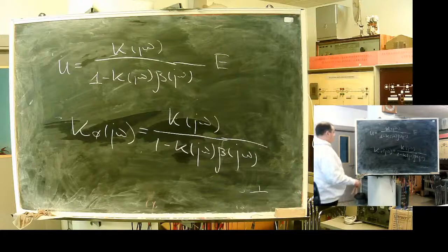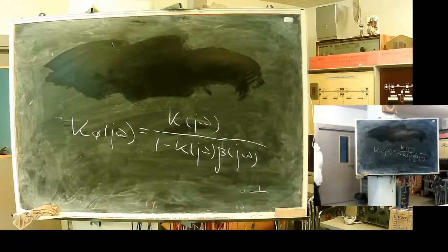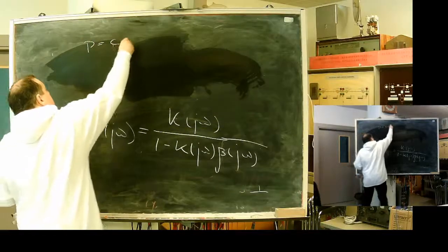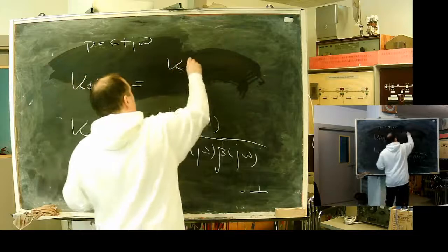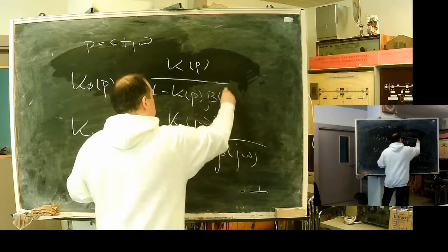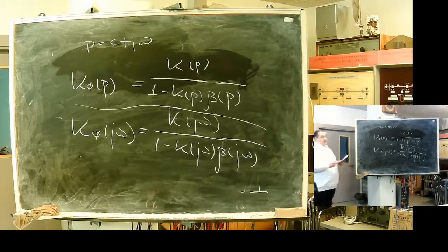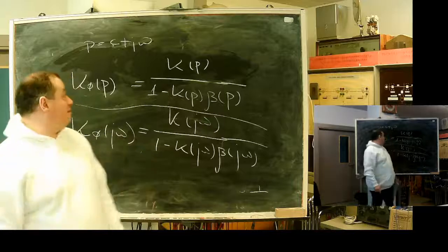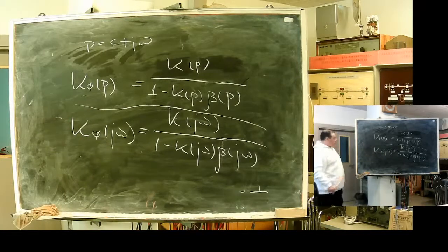Here it is the synthetic characteristic. In terms of the Laplace transform, to make it universal, if P is the complex frequency, the closed loop transfer will be our amplifier transfer over 1 minus amplifier transfer times return transfer. Here C is a constant. That is the resulting transfer in the Laplace transform, in Laplacian space.